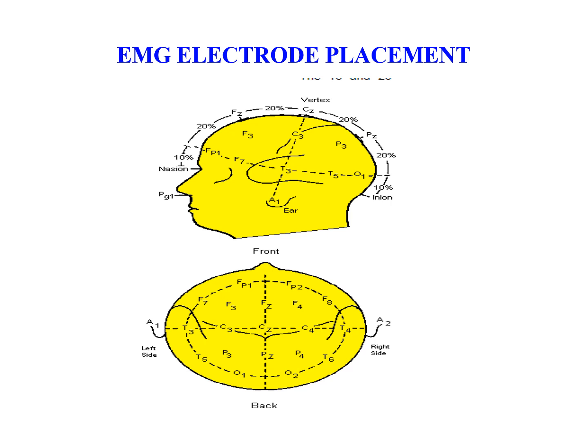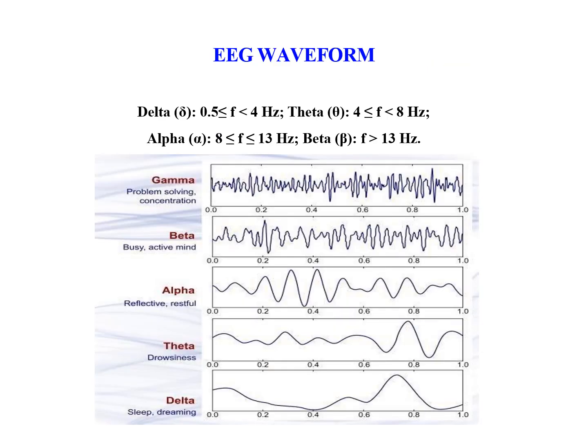This is the placement of the electrodes for electroencephalogram signals, EEG signals. The electrode placed in the frontal lobe is F1; odd numbers are in the left hemisphere and even numbers in the right hemisphere. The nasion is between the forehead and nose. The inion is the back of the skull. This is the diagram of the electrode placement of the EEG 10 to 20 lead system. This is the EEG waveform.